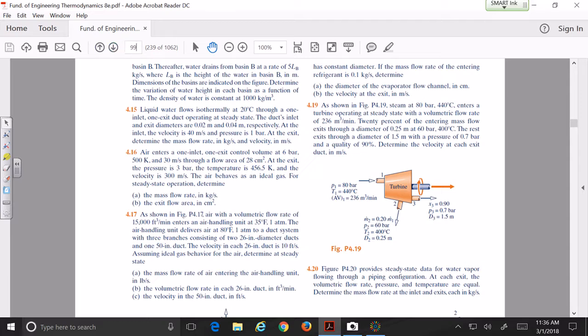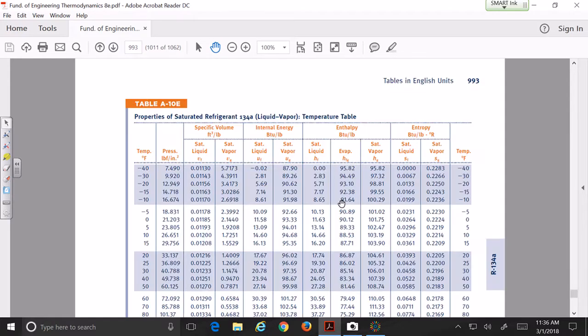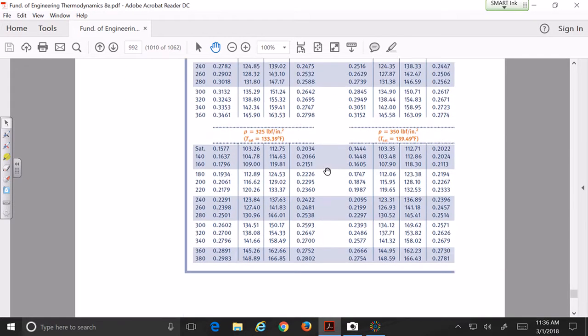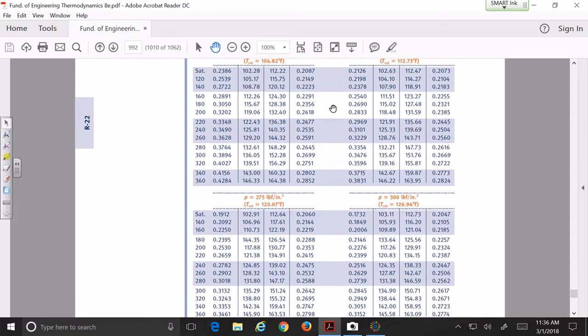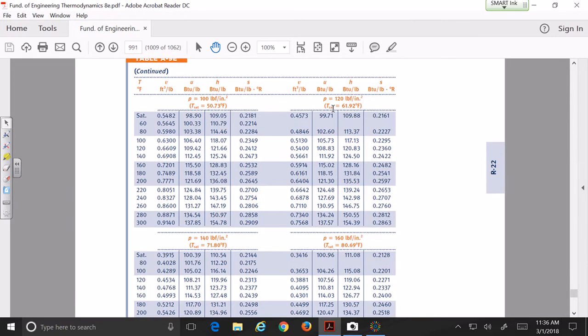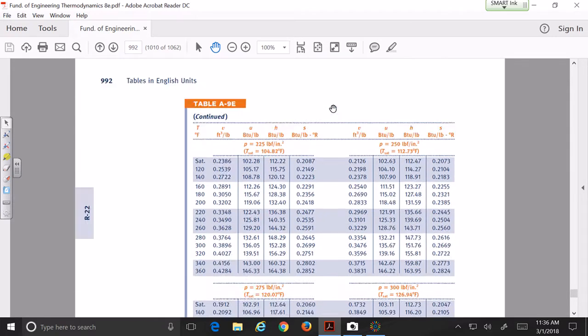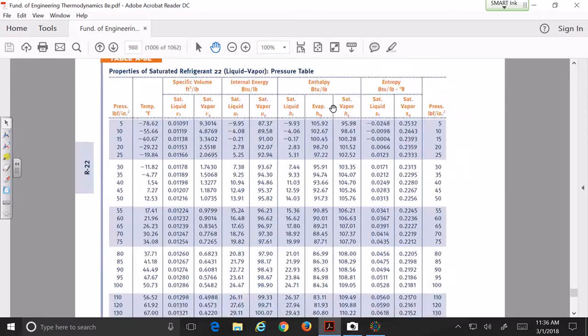So, since we have this figure, now we're going to look at what's happening here at 2, no? So first, what is the state of the water at 2? I think it's still going to be steam, but what is the pressure? Pressure is 60, no? Temperature 400. So, I'm wrong with the table. Oh no, maybe 83, so we need 84.